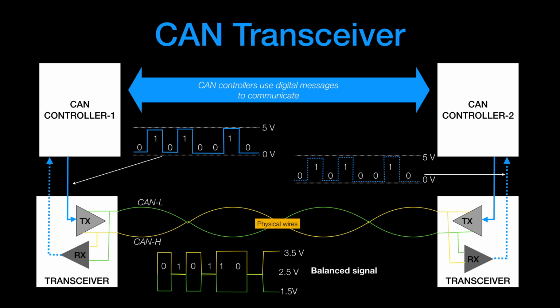Balanced signals transmitted by a transceiver are always seen immediately by the same transceiver on its own receive. That is internal circuitry on those transceivers. Also note that all transceivers are connected at the same time in parallel to the same CAN bus. So in other words, if one is transmitting, then everybody else can receive. And that is why you will hear quite often the term CSMA/CD, carrier sense multiple access with collision detection. Very similar to what you see on a local area network.